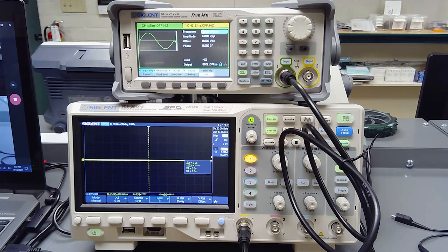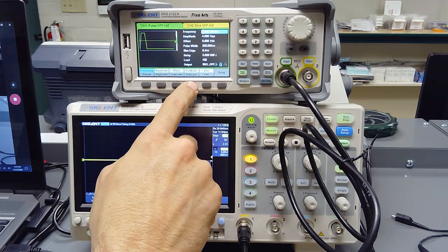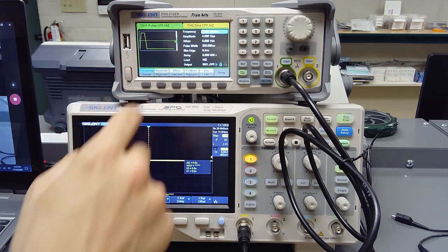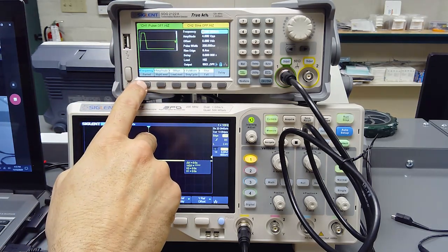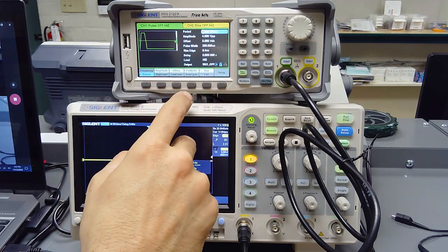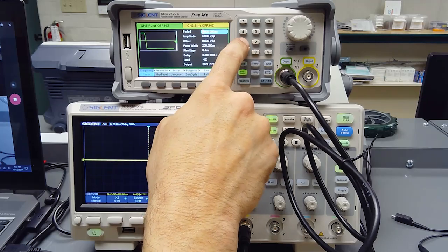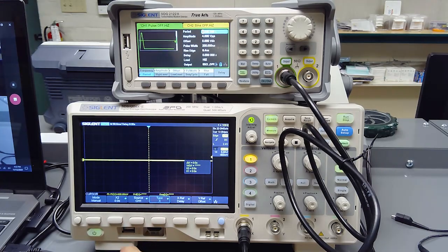And so the way we're going to set this up, I'm going to set up a square wave that is sending a short pulse every 1 second. So the first thing I want is to go to this pulse feature. This is basically a square wave with a long delay. We're going to say, instead of frequency here, we're going to go to period, so we can define it in time. I'm going to say I want this every second, 1 second. So every second we're going to get one pulse.